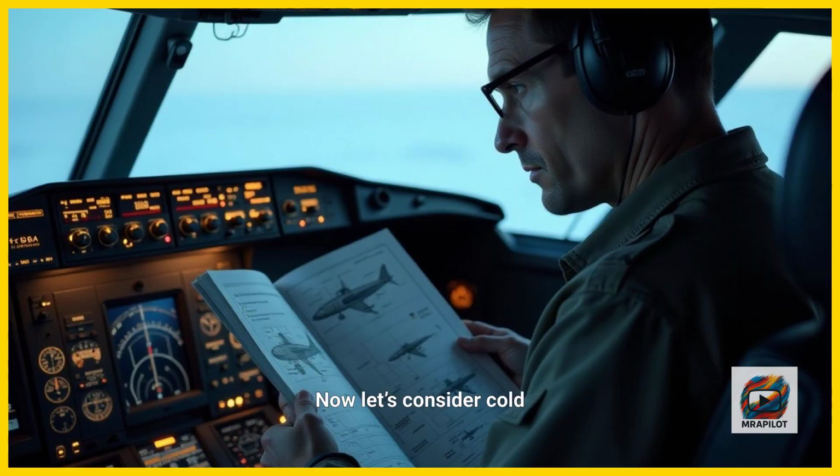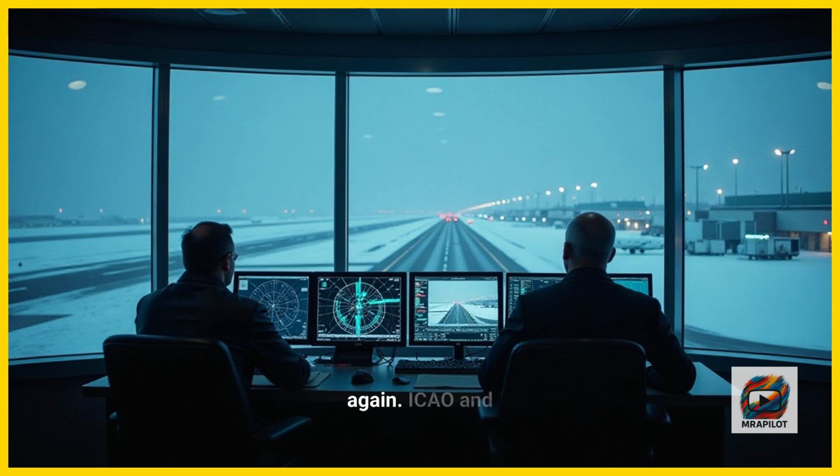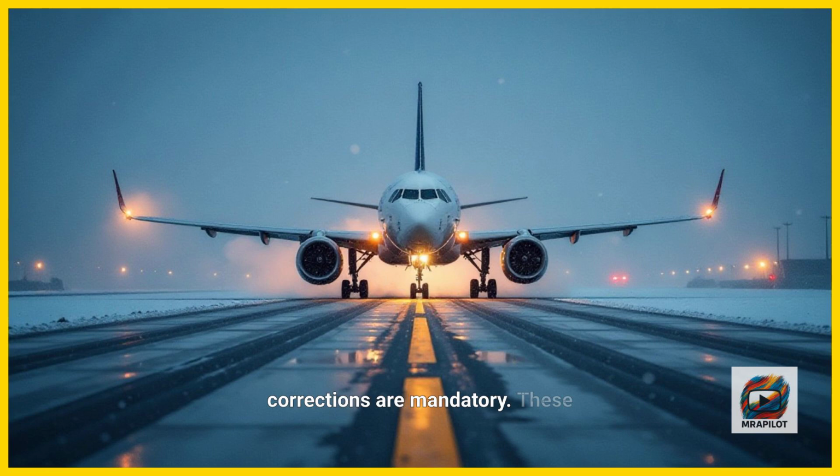Now let's consider cold temperature operations again. ICAO and national authorities may designate specific airports or runways where cold temperature corrections are mandatory. These help ensure that aircraft don't descend below minimum safe altitudes on approach.